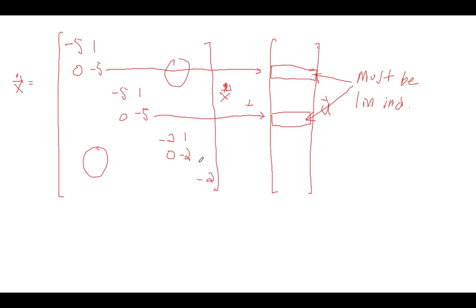If we go down to the -2 eigenvalues, the same basic rules apply. So I know the bottom row of this Jordan block has to be non-zero, and I know the bottom row of this Jordan block has to be non-zero. In this case, it's a 1x1 Jordan block, but that's still the bottom row of it. Those two bottom rows have to be non-zero so that you have control over those states.